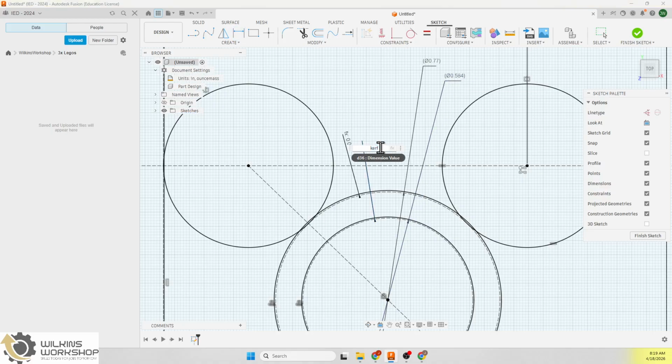So if it's not kerf, it might be kerf divided by 2. No. So it's going to be kerf times some fraction. So I think it's 3/4 on this one. We're going to leave it as 3/4, and this is where we might have to make an adjustment based on your 3D printer on these numbers.